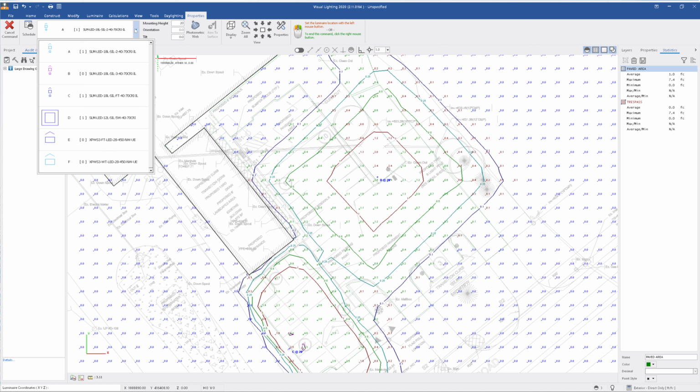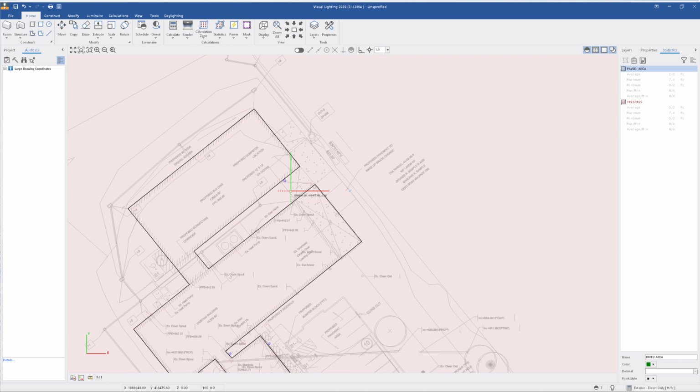Okay, on this last one, you can see my building, my calculation zone, my light's a little bit outside of that. You might have to adjust that. It should be okay in this case. Okay, so I just added 1, 2, 3, 4 building mounted lights. Hit the calculation, you look at the stats, and you say, okay, my average is now 1.2, but I still have zeros. And those zeros are up here at the front.